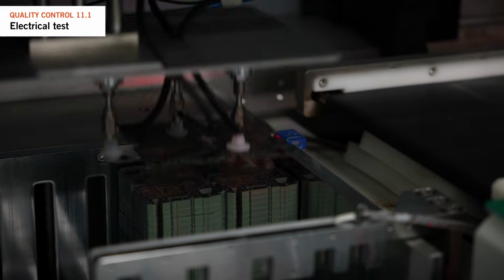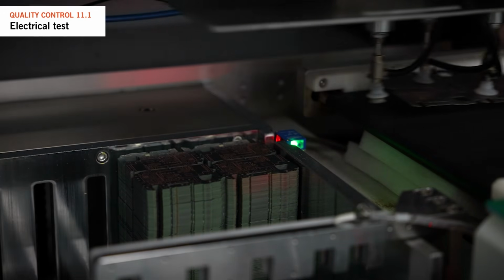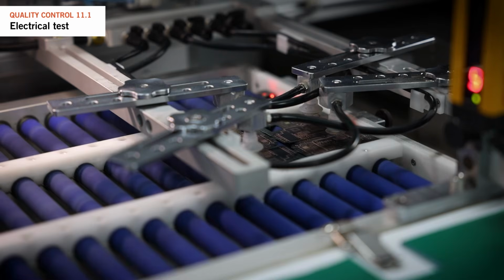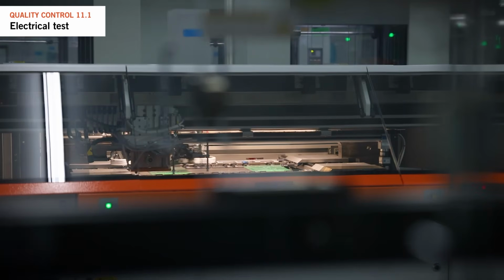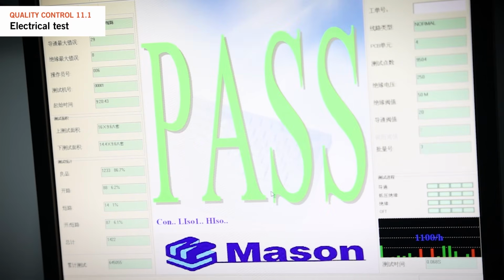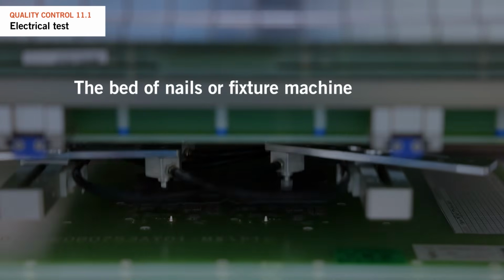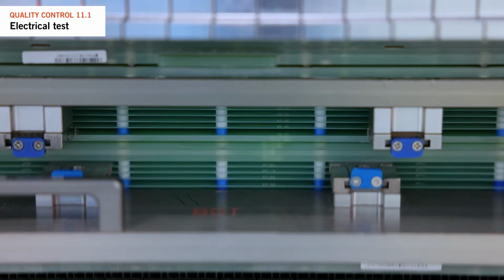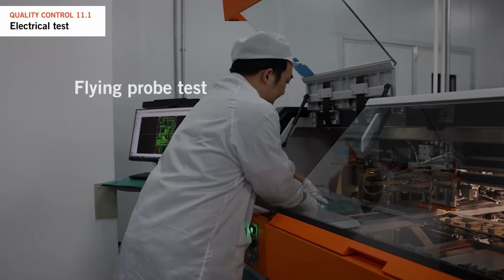To make sure all the circuits are correct and have the right connections, we test every PCB electrically. We look for any unexpected open or short circuits, ensuring everything works as it should. There are 2 common ways to test for basic open and short circuits. One is the bed of nails or fixture machine, suitable for checking large batches in high volume. The other is the flying probe test.